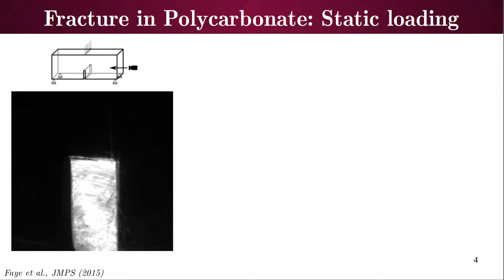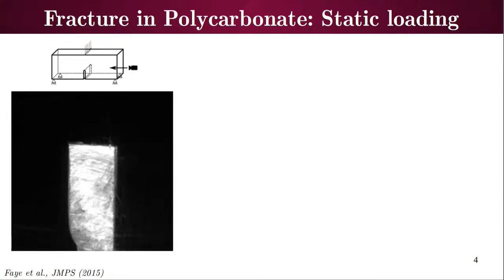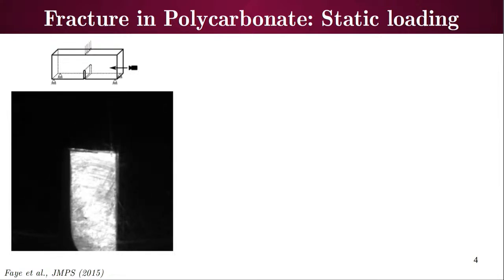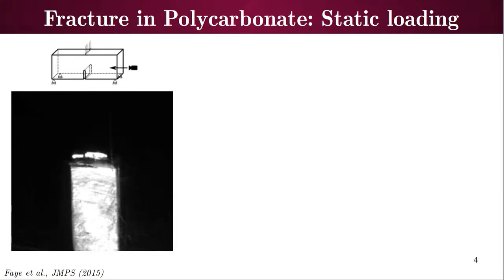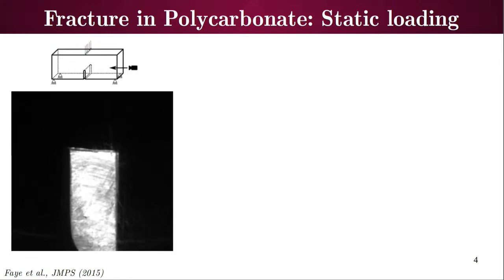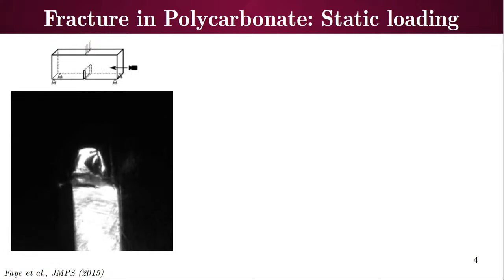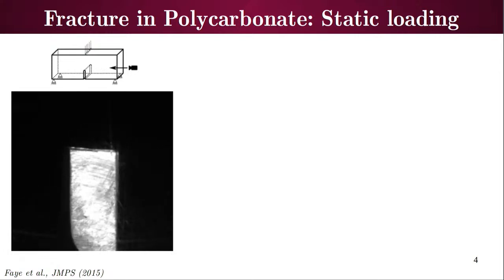In the center, because in between there is a plane strain condition and the triaxiality is higher in between. So that is where the chances of growing are higher. That's why it comes at the center. Because towards the surface it's a plane stress condition. The stresses are zero at the surfaces, whereas inside the material there are stresses in every direction. So it is easier to grow at the center compared to at the surface. Okay. Thank you.